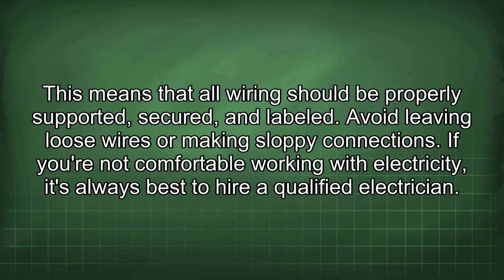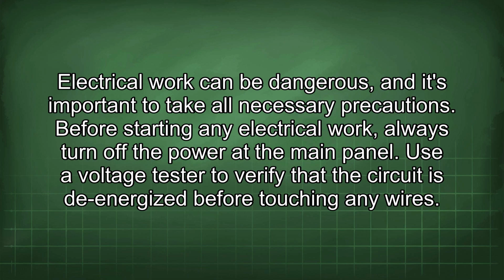If you're not comfortable working with electricity, it's always best to hire a qualified electrician. Electrical work can be dangerous, and it's important to take all necessary precautions. Before starting any electrical work, always turn off the power at the main panel. Use a voltage tester to verify that the circuit is de-energized before touching any wires.